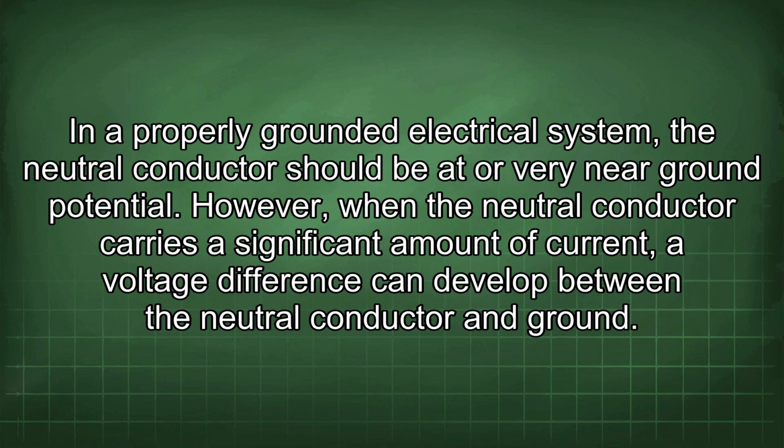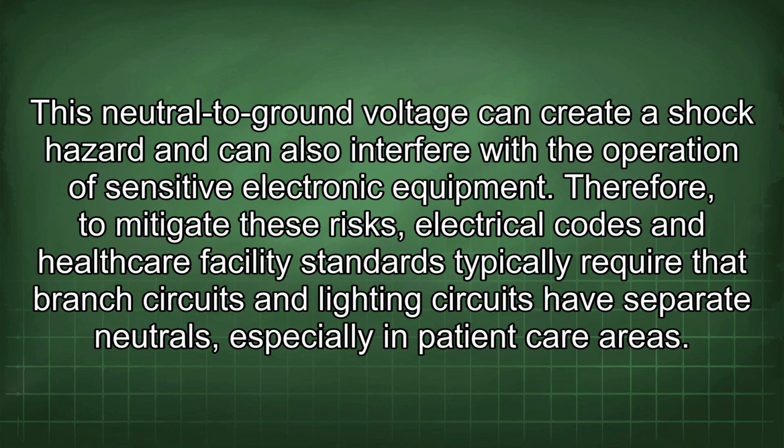In a properly grounded electrical system, the neutral conductor should be at or very near ground potential. However, when the neutral conductor carries a significant amount of current, a voltage difference can develop between the neutral conductor and ground. This neutral to ground voltage can create a shock hazard and can also interfere with the operation of sensitive electronic equipment. Therefore, to mitigate these risks, electrical codes and healthcare facility standards typically require that branch circuits and